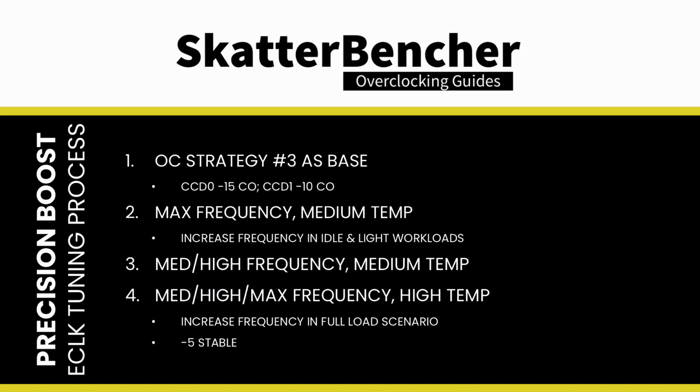Here I found that there's enough margin to set a -5 curve shaper. In theory, this should give us a little more performance in high load scenarios. To illustrate how curve shaper builds on top of curve optimizer, I want to share two VF curves.